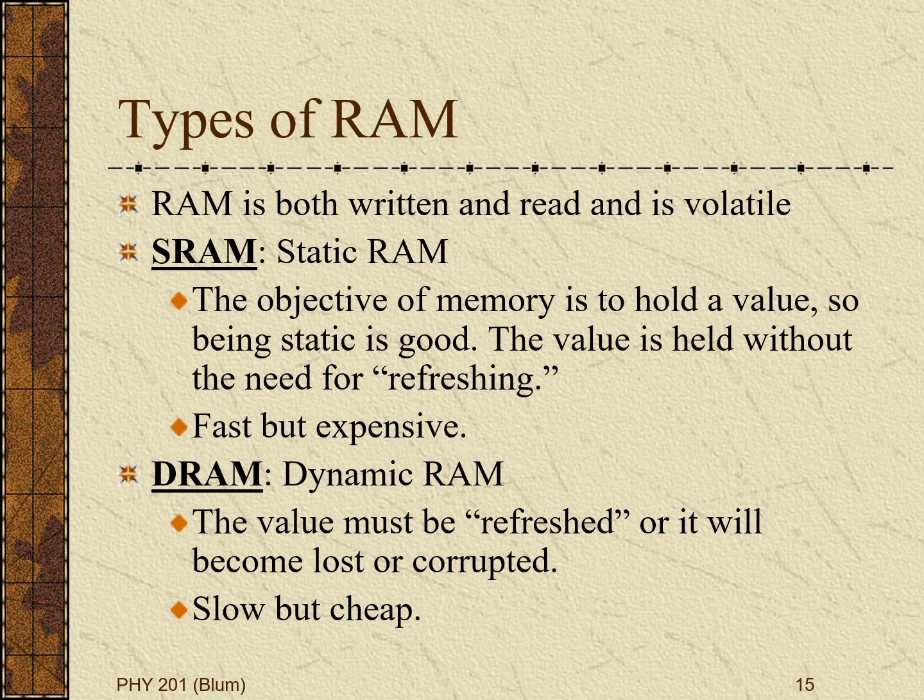So with dynamic, you've written, say, a 1, and then that 1 is being lost and will need to be refreshed. And the good thing about static RAM is that it does not need this refreshing. And so it's going to be faster, but it's going to be more expensive, whereas DRAM, dynamic RAM, is slower but cheaper.